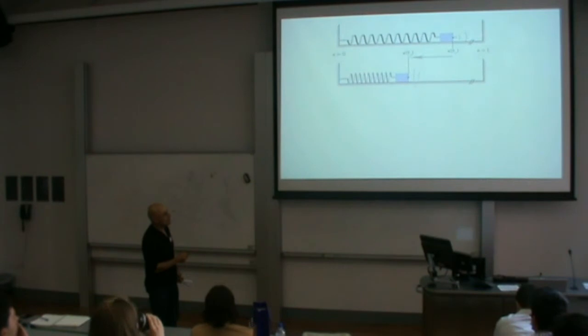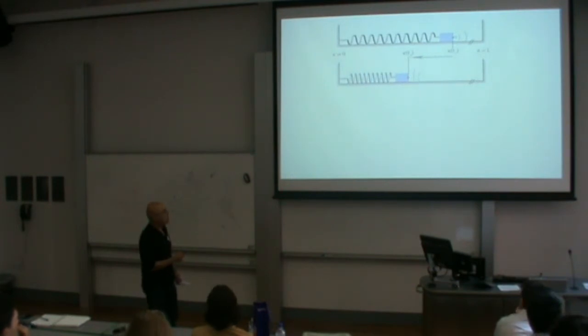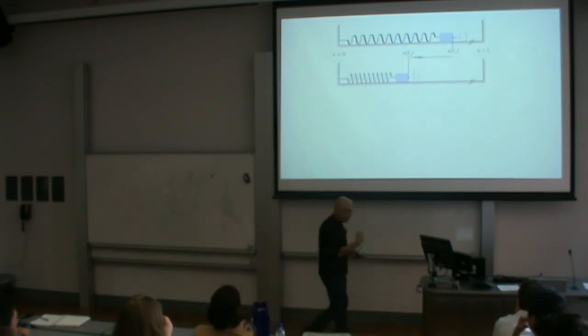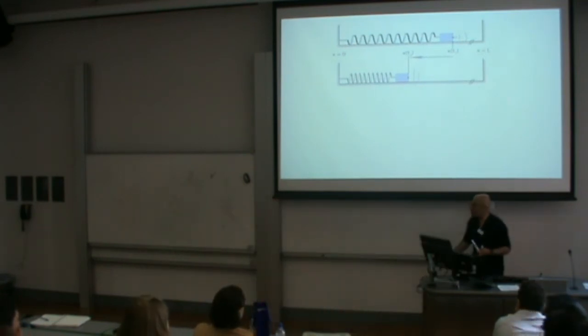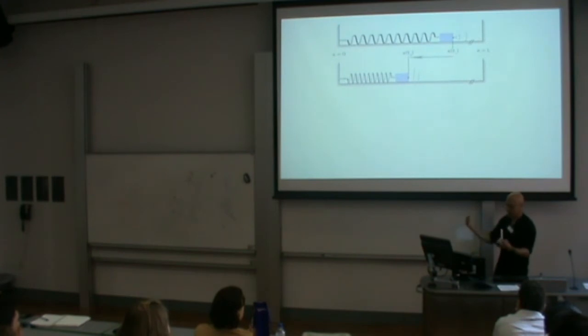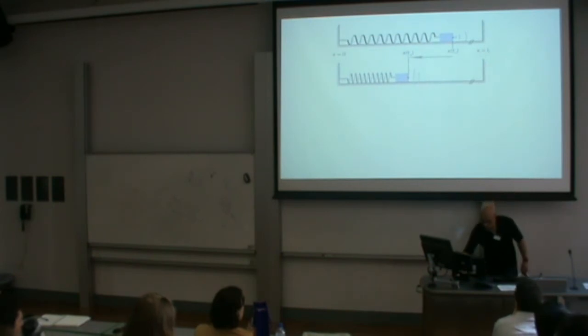The sound will move in the right direction, will be reflected by the wall, will come back, and will be received by the receiver, which is at the same position at time t2. So we have some kind of state estimation problem with intertemporal measurements. And this often happens when we do some SLAM problems where the robot has to do loops. We will have such intertemporal measurements.